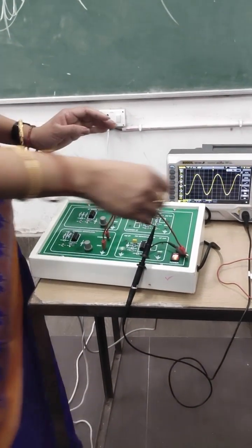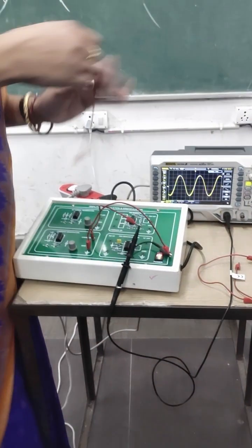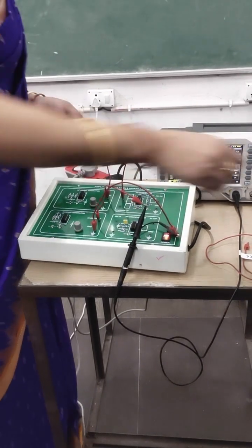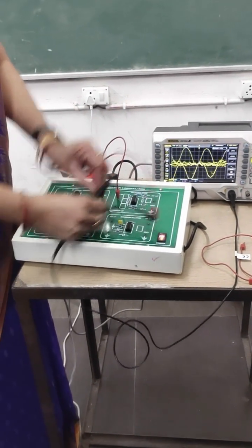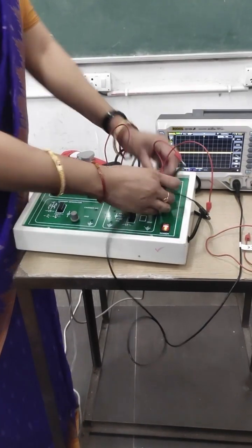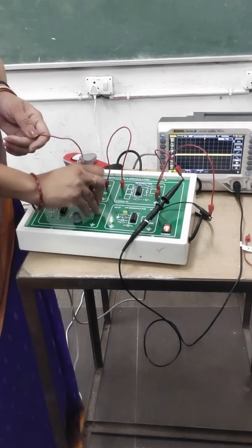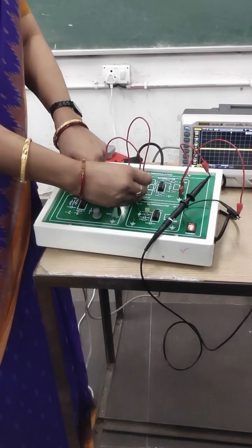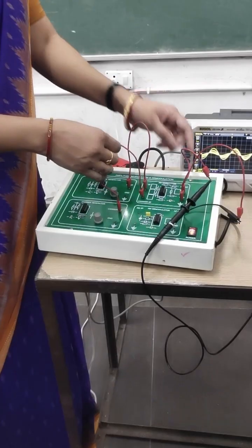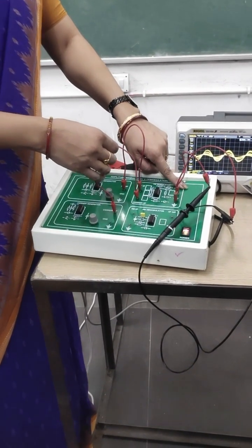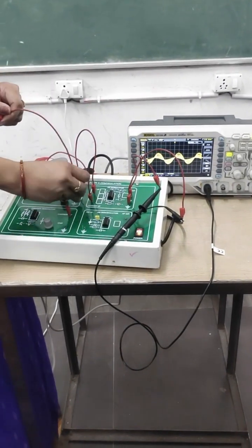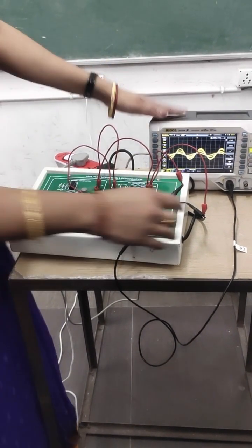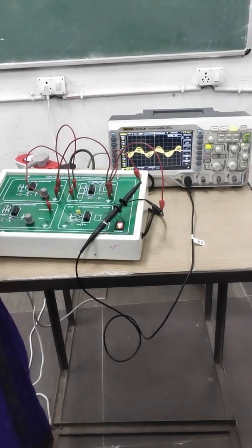Okay. Now we will supply these two signals to the modulator. So supply this signal to this. What I am doing carefully is supplying the message signal to the AF input, and the carrier output will be connected to carrier input. The output will be seen from the AM output part. All the grounds are connected. Now just press auto and wait for a while.